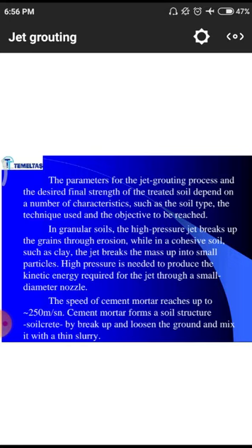So we have to give the material point to point, so that there is no erosion of the surrounding soils, especially these granular soils and cohesive soils. Whenever we are treating these two kinds of soils, we have to go for this point source of filling.